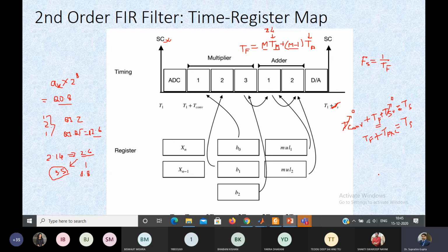Because we have this FIR and IIR structure, and with this structure, since the outputs are also taken into account in case of IIR, it will be a little bit slower than the FIR with the same order, because the number of multiplications and additions are getting increased. Therefore the IIR implementation of the same order will have a smaller input frequency range compared to FIR. Right.